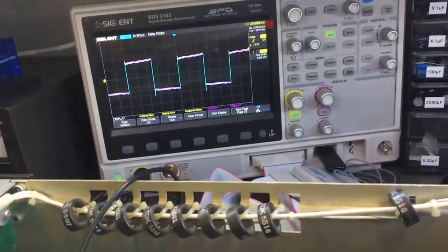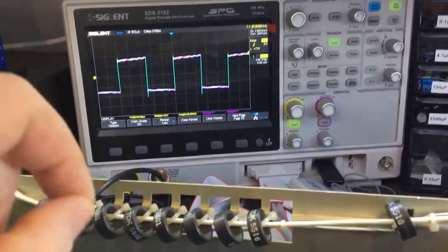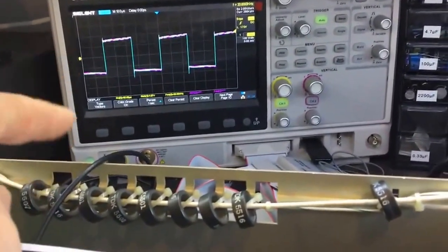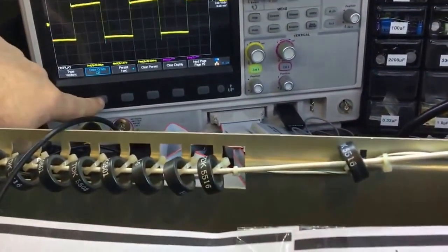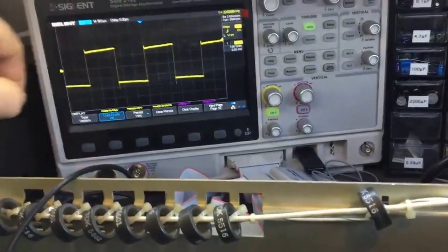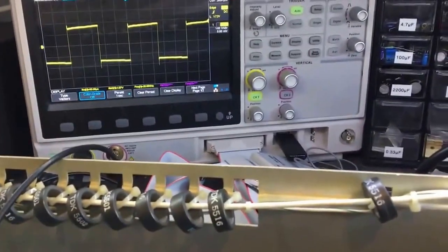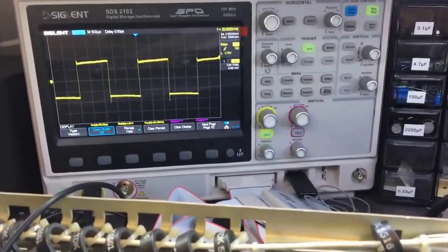So I've actually got two scopes hooked up. I've got that one there because it's good at showing glitches. It will show if something is glitching at all. And I've got the colors on and stuff on it, but I'll just have a look again. Actually, I think it doesn't help. I've got persistence on as well, so it stays on the screen longer if it does glitch. Which is one of the handy little features of the scope.